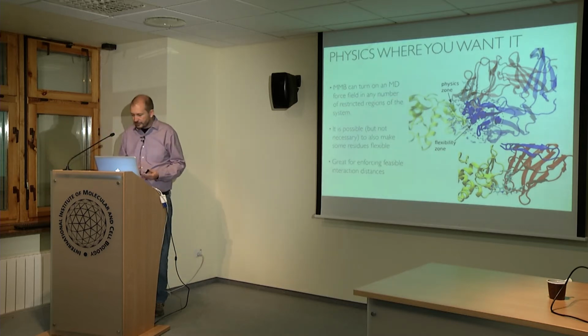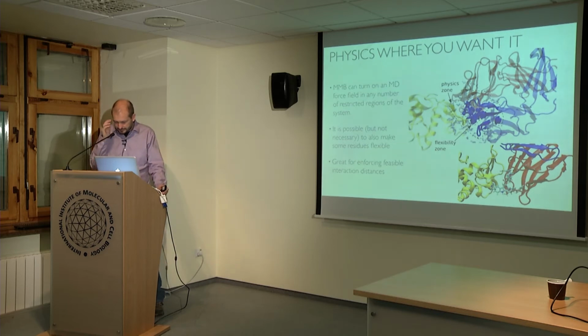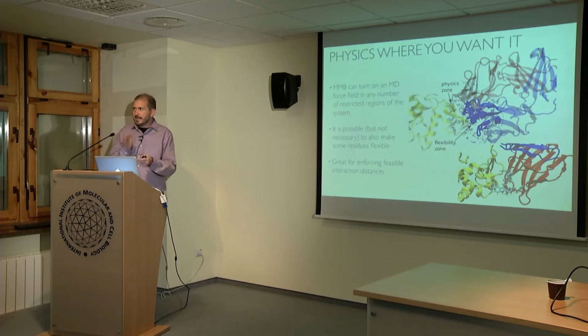And there's a second reason that it's more likely to converge, is that we have what's called a variable time step integrator. And that means we can make the time steps really tiny. The time steps are not fixed. So if it needs to take a shorter time step to resolve some very large forces, then it can do that.